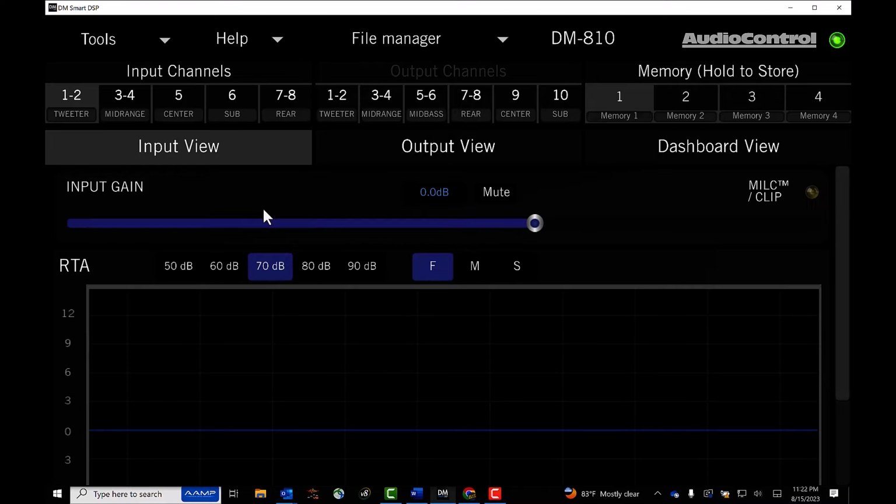even implemented properly, was removed to free up a lot of DSP resources and to make room for the more useful and desirable improvements which we've made. The input gain slider allows a range of gain adjustment in the analog domain before the analog to digital converter. This allows the DM810, 608, and all the D-series amplifiers to have an unmatched compatibility to maximize the headroom as well as reduce the noise in the system.